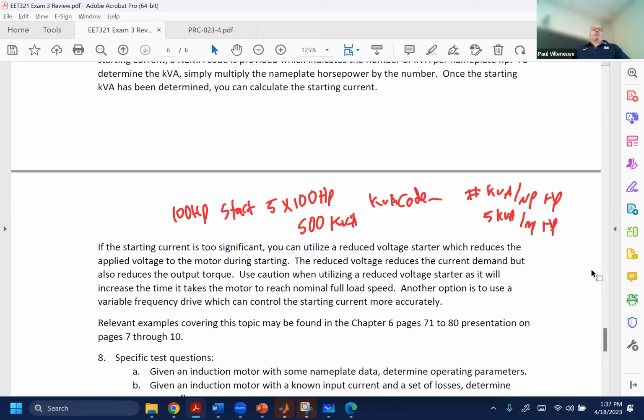So transformers are more efficient because when the oil gets hot, natural circulation carries the hot oil away and you've got cool oil there. So the resistance gets to be lower. Oil filled transformers are much, much better and last longer. But some places you can't have them. Like if you're near a river, you probably don't want 1,000 gallons of oil spilling into the river.